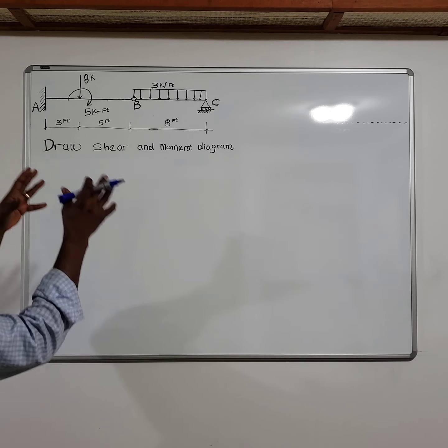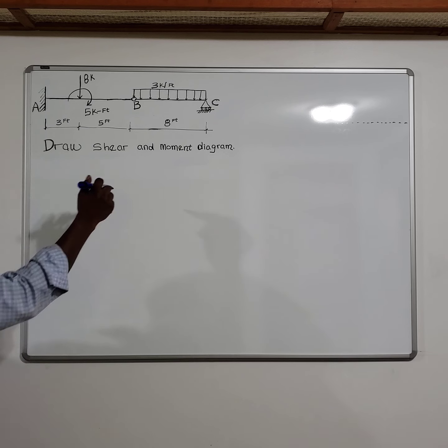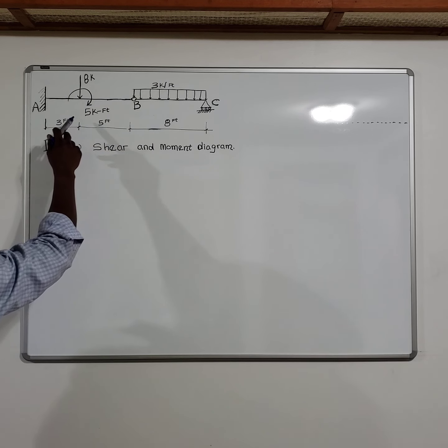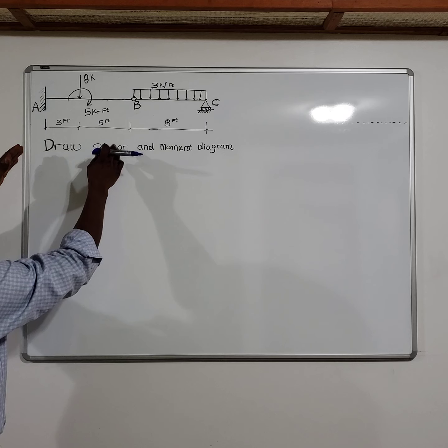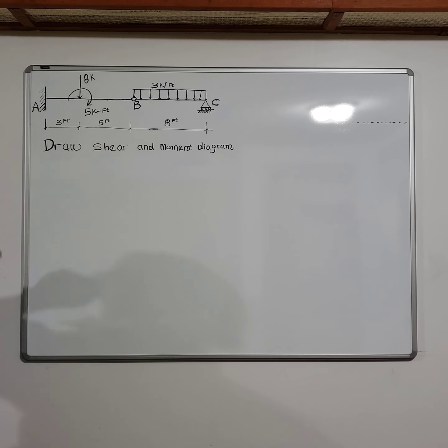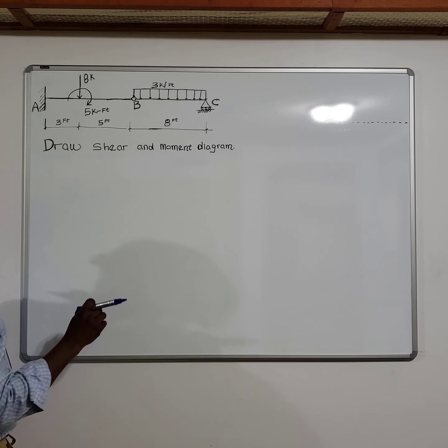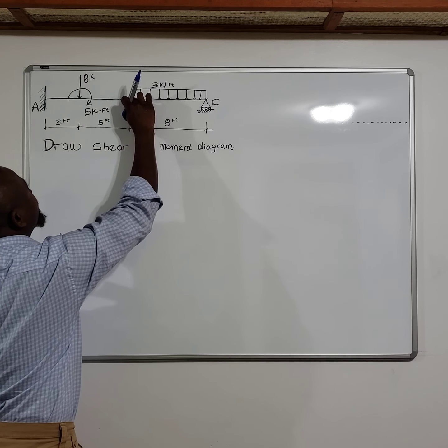So you can start with that section and solve that, and then transfer your known value for the internal shear at point B to the first section of the beam, and with that, you will be able to solve the other two reactions here. So let's start. Without drawing an additional free body diagram, let me just introduce my shear at this point here.